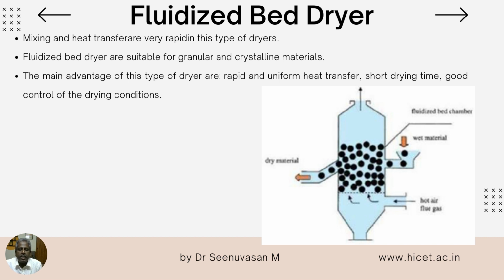Understanding this concept of the fixed bed and the fluidized bed is very important to understand the fluidized bed dryer. Now, I will explain the fluidized bed dryer. A fluidized bed dryer consists of a steel shell of cylindrical or rectangular cross section. Again, I am telling you that this is a cylindrical or rectangular cross section. A grid is provided in the column over which the material rests.